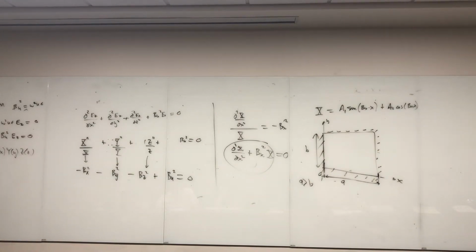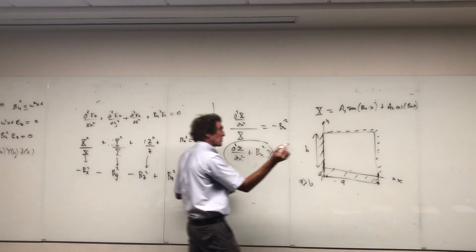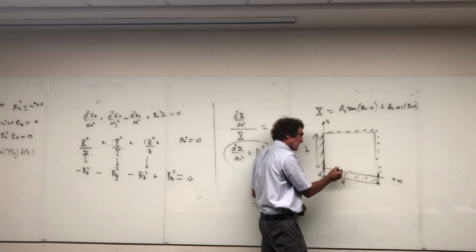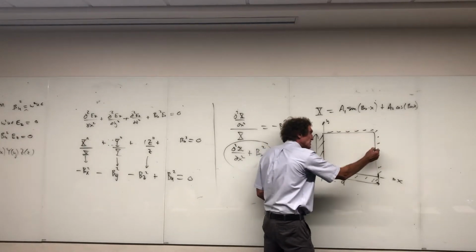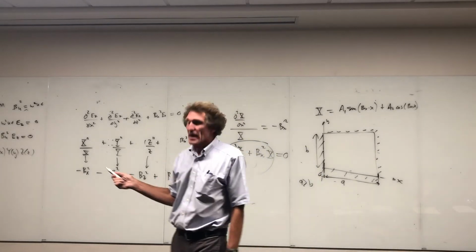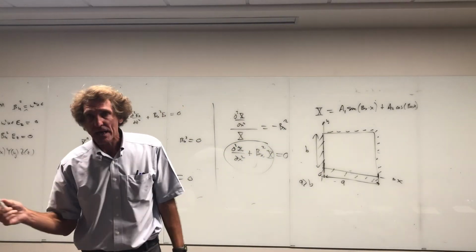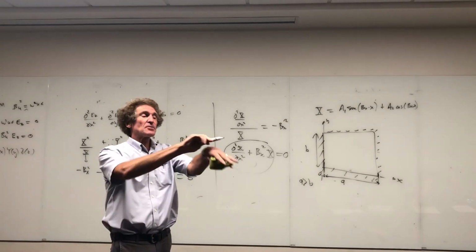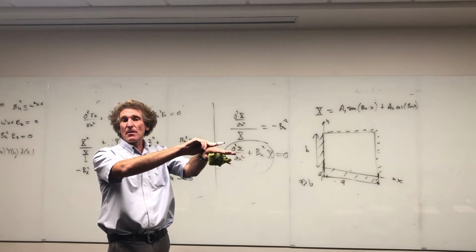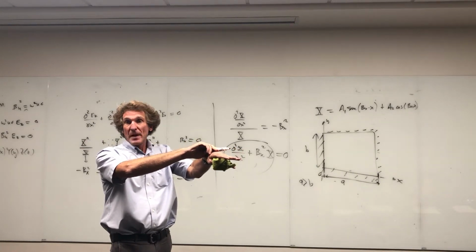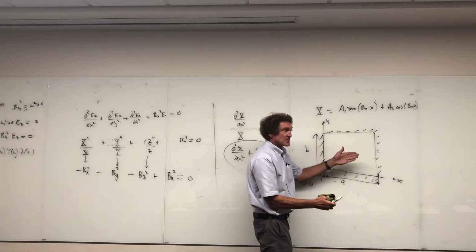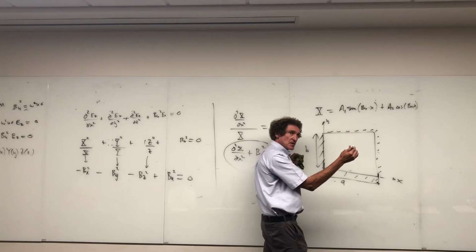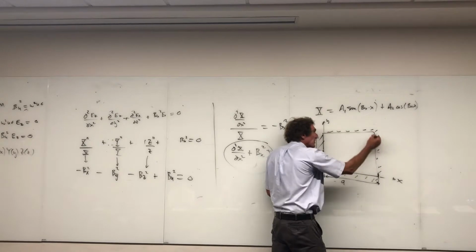Now pay attention to this. Well, EZ is in the direction perpendicular to the board, right? I want you to think about this. What's the value of EZ at this boundary, or this boundary, this boundary, or this boundary? Anyone? Is it 0? Why is it 0? You're right. E tangential is 0 on a perfect conductor, right? Do y'all remember that? A conductor cannot allow an electric field to exist. It'll short it out. Basically I took a long pipe and cut it in half, and I'm looking at it. The E field is in the Z direction, right? That means it's got to be 0 everywhere, right?